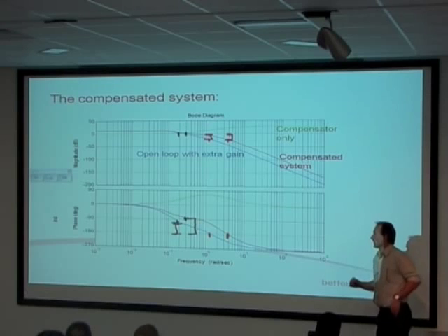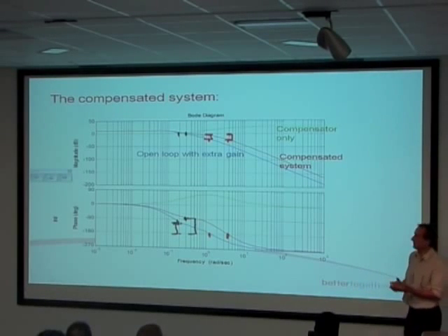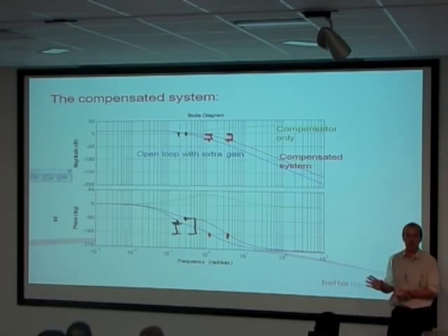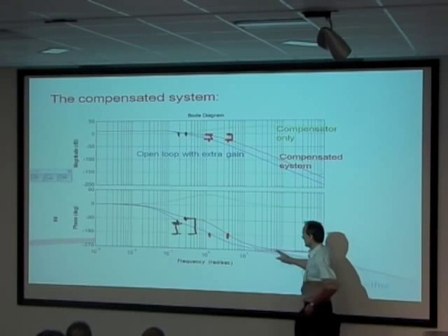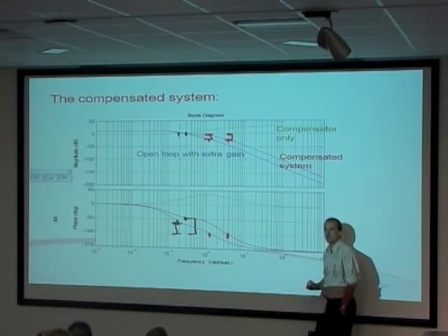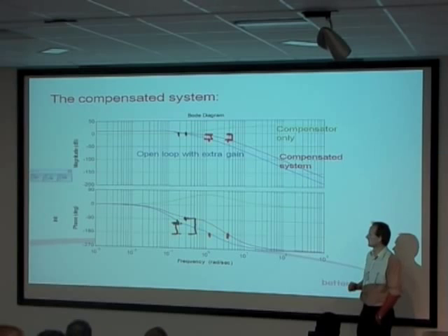Okay, so all of these things are to do with compromise. The fact that we're putting in more gain, generally speaking, isn't such a good thing for stability in a closed loop. But the fact that we can fill in this big lump of phase lead, I can use that to compensate for it.